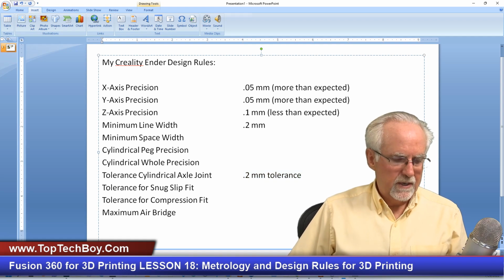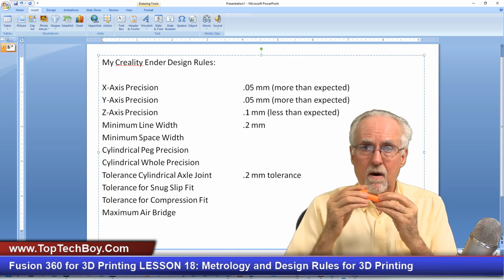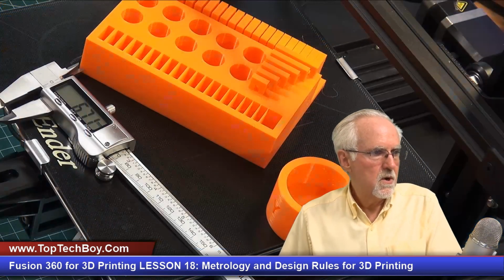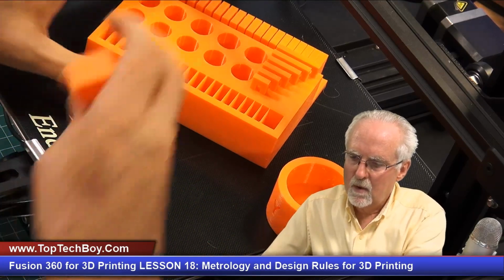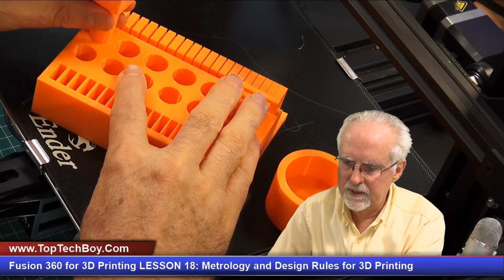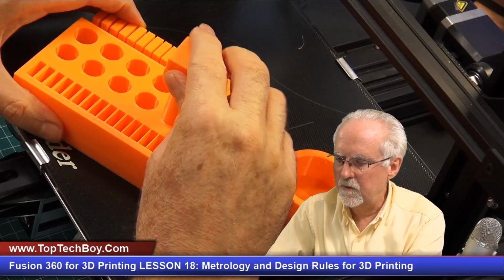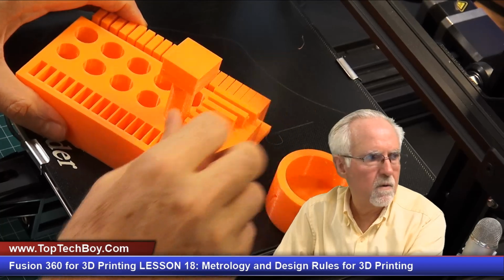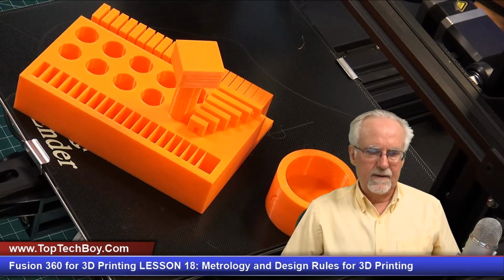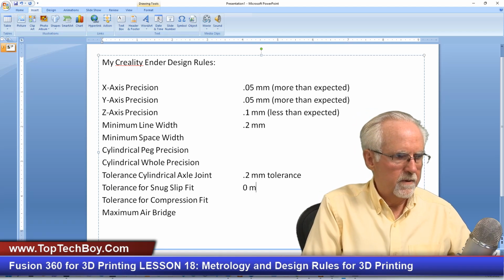Okay, now let's see if we can get the tolerance for a snug fit. That would be something that would slip on and slip off, but hold snugly, like our eyeglass cases. What tolerance would we want there? Well, if I come up here to 15.1, that is too loose. If I just turn this over, that could fall off. But if I come over here to a 15 hole and a 15 peg, that I would say is a tight fit. So the tolerance for a snug fit would be 0 millimeters.